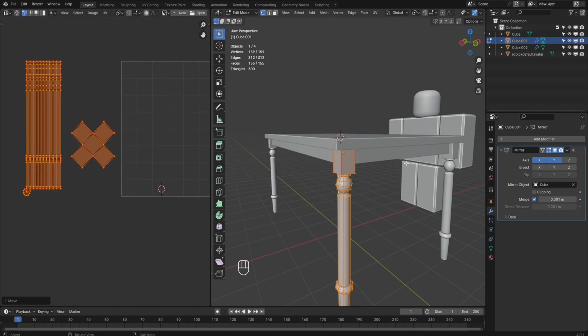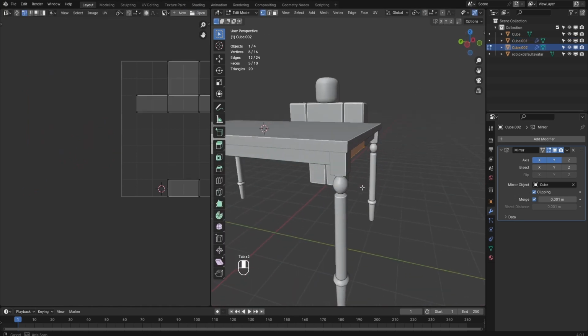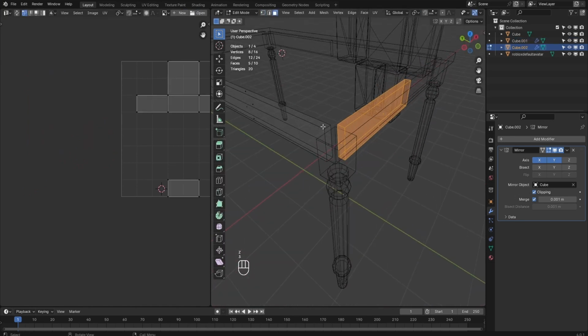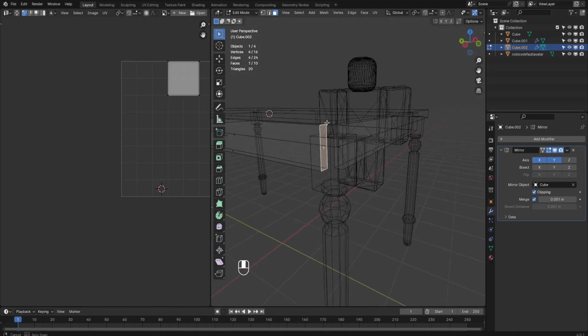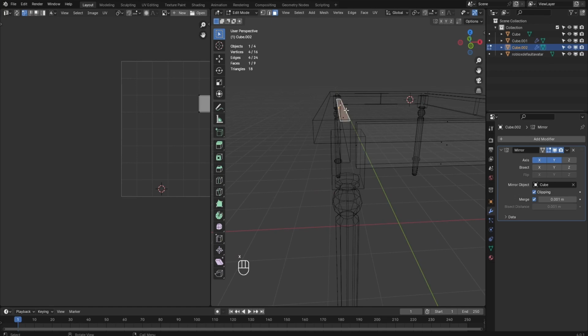And now we're moving on to the boards, and you notice that there's geometry savings there too. What we're going to do is delete any interior faces. So we're going to delete the side and the top of each board. To save extra UV, I'm only going to UV the sideboard and duplicate it over.